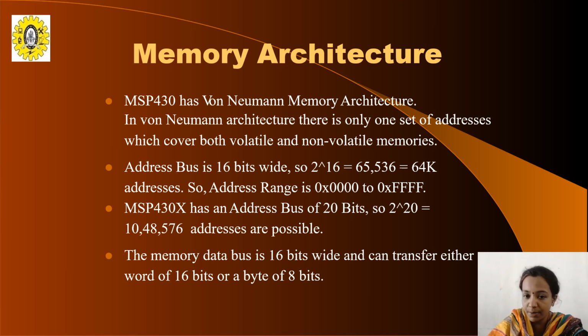MSP430X has an address bus of 20 bits, which means that the address can be in the range of 2 power 20, which is nothing but 10 lakh. So 10 lakh addresses are possible. The data bus is 16 bits wide and can transfer either a word of 16 bits or a byte of 8 bits. So this is about the architecture of MSP430.